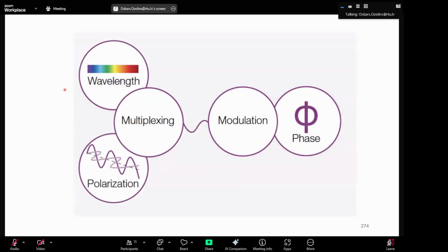Right, and as we already looked, typically for wavelength and polarization we use for multiplexing. So for polarization we use 2 different states of polarization: X polarization, Y polarization. And these polarizations are so-called orthogonal. What does it mean? If you have 2 orthogonal signals, they do not interact. So you can use these orthogonal signals as parallel data channels. And yeah, so this is what is used.